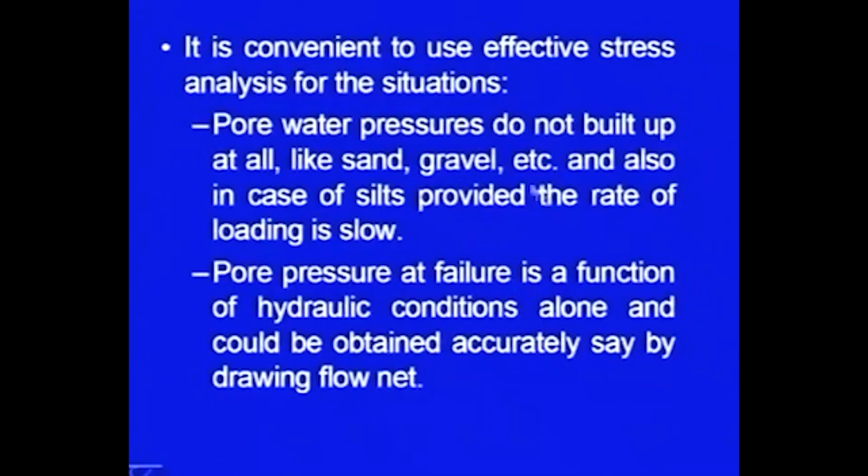So, for example, effective stress analysis can be used in case of silts provided the rate of loading is slow. If the rate of loading is slow, there will be some rate at which the dissipation of excess pore water pressure must be taking place. So, if this loading rate is slow and the dissipation rate is higher, it can be considered as a drained situation. In that case also this effective stress analysis is used.